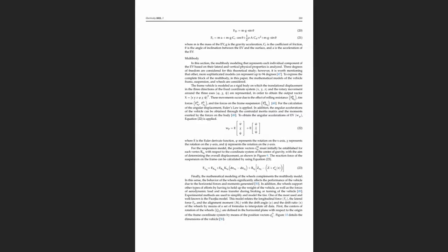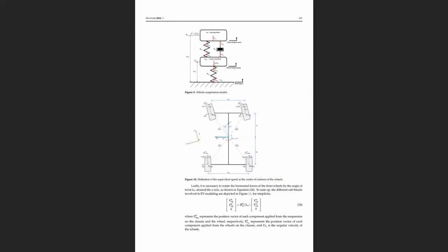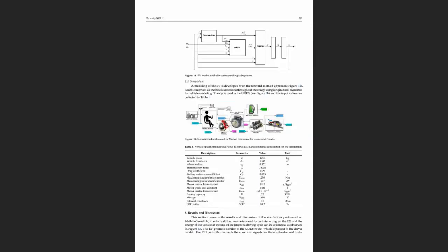This is your total force demand, and then we are expecting from you the torque value. Torque value is equal to radius times force, Newton meter. Where does it come from? Wheel radius. Now we have this parameter.